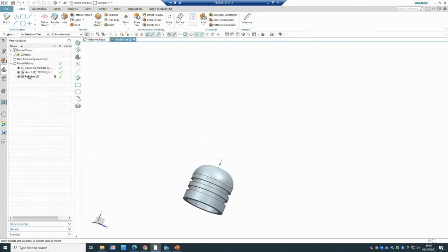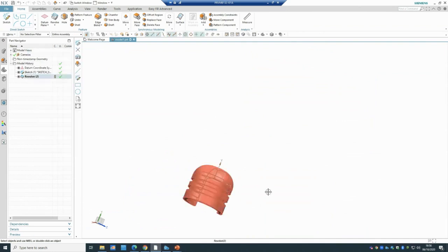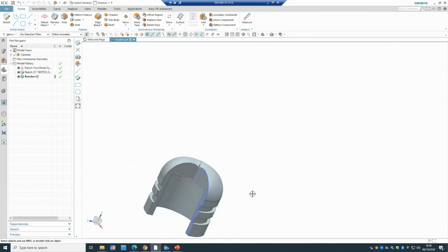If I want to change that one, this one is a full 360. Let's make it 270 so you can find out what's going on with it. And that's the revolve. So we have extrude, we have revolve, we have extrude cuts as well that I mentioned last week for you. I will do it again here, which you call extrude subtract. So is everything happy with what I covered for the constraint, dimensions, and also revolve?